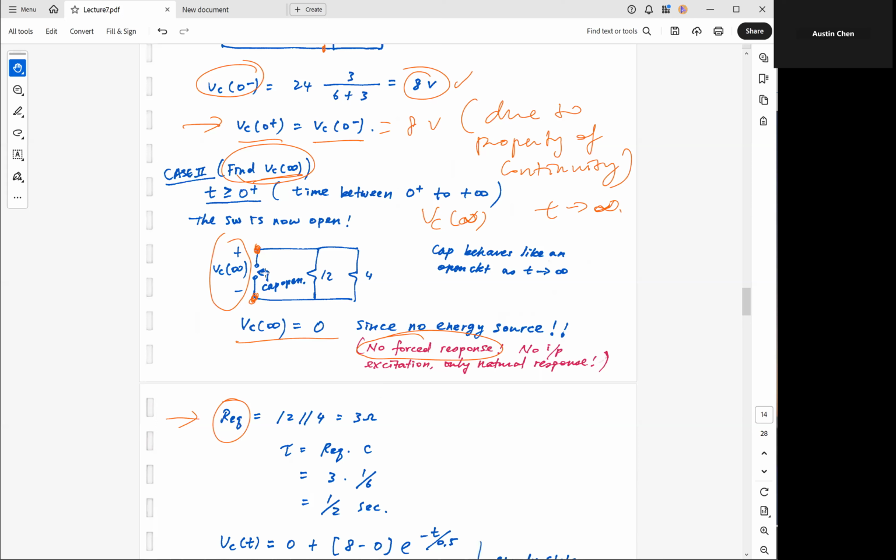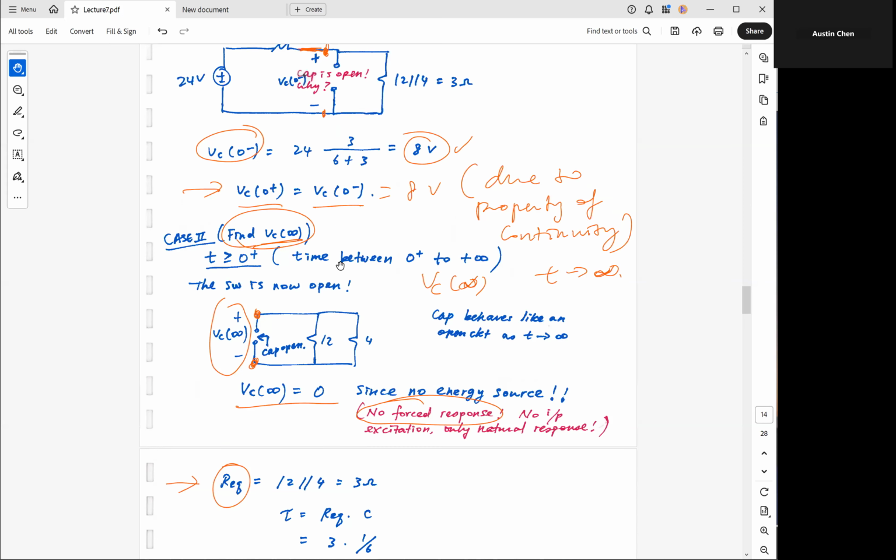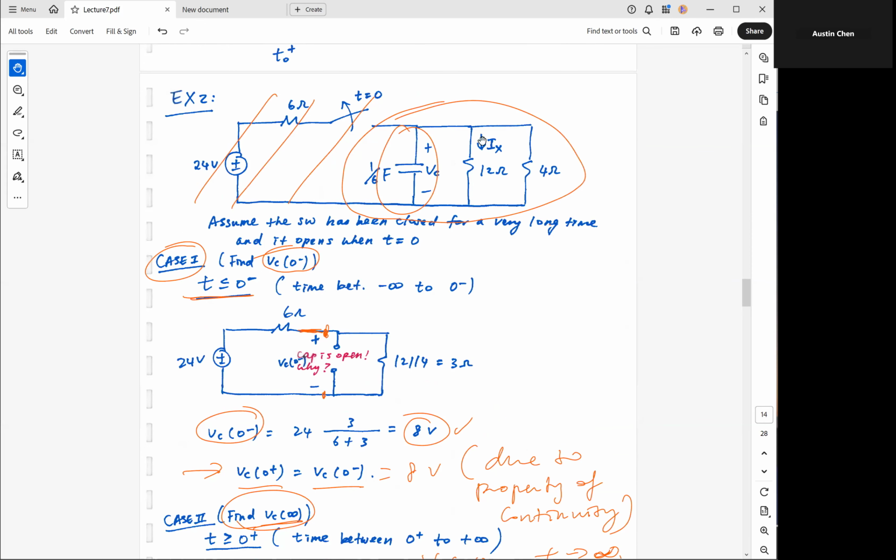And to find this REQ first, you have to imagine you're this capacitor here, right? So now you can put back your capacitor, or you can even go back to this circuit here. You imagine you're this guy standing right here, you're this capacitor, and you look all around you. When you look to the left, you don't see anything because now you have this switch that is disconnected from the rest of the circuit.